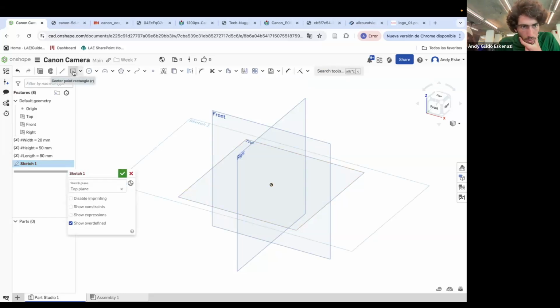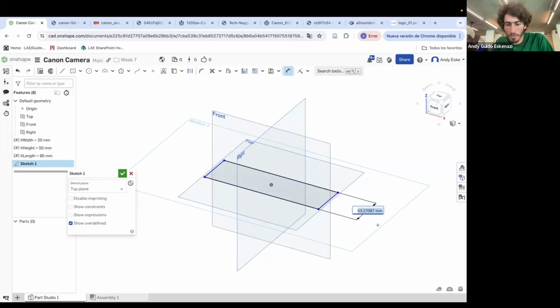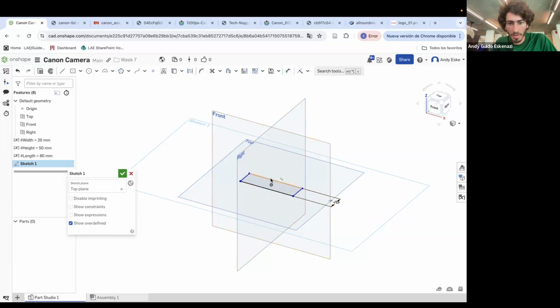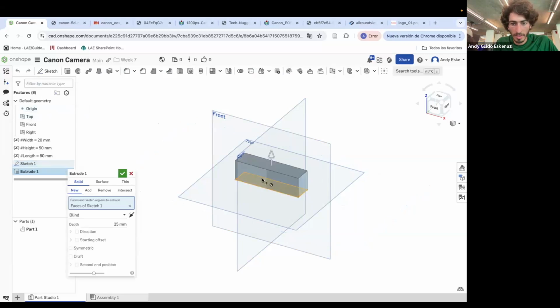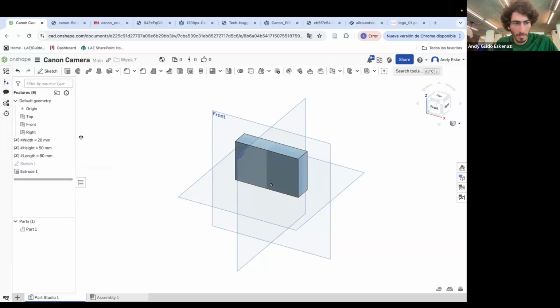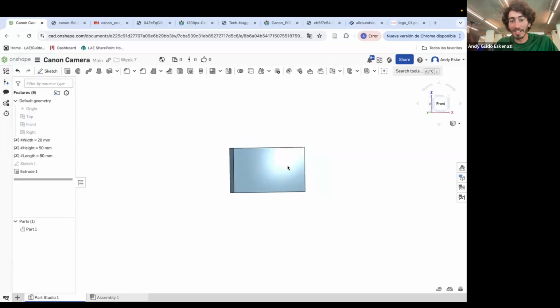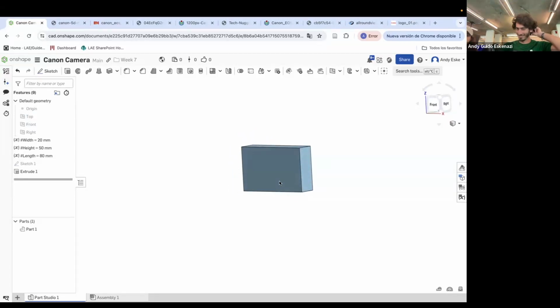And let's do it. So let's do a rectangle. And I'm gonna click on D. And I'll make the width the hashtag symbol width, then the hashtag symbol length, and then the height, hashtag symbol height. I like the size, the size looks decent. Okay.